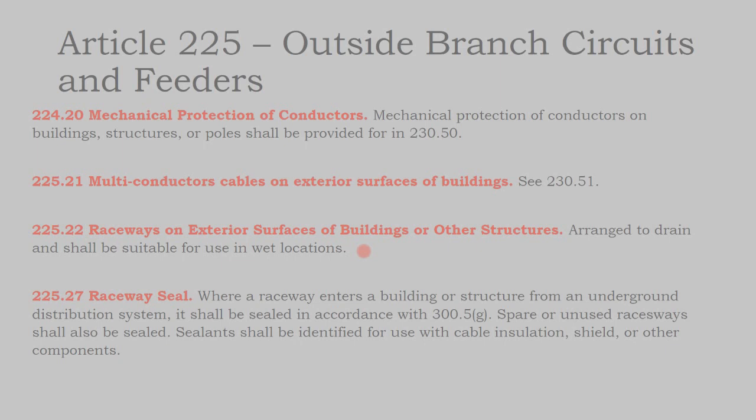The fault was that while the pipe was in a pipe boot, the contractor did not put additional sealant between the pipe boot and the fitting inside the box. So water was getting into the box and then falling through the conduit into the attic.